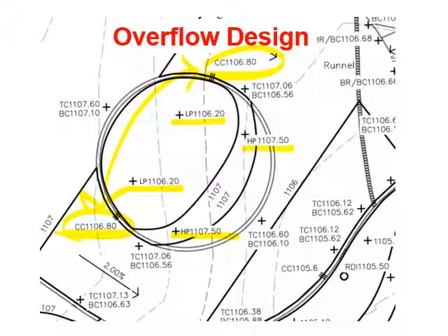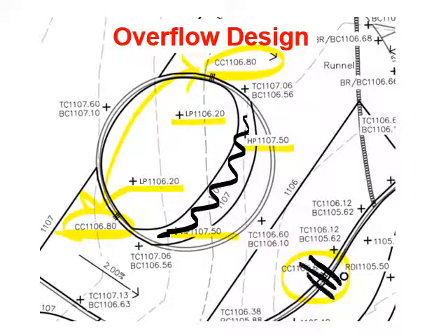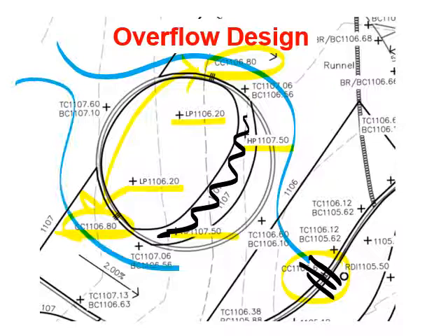There's obviously the berm that's created by those high points. And then the elevation of the curb cut down here is independent of the turnaround. It's based upon the parking lot as the water continues to run down around this system after it's filled and runs into that curb cut.